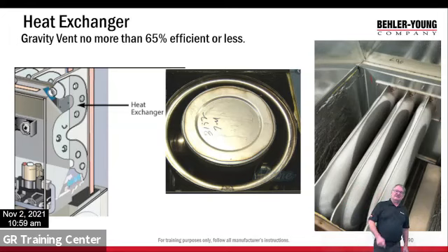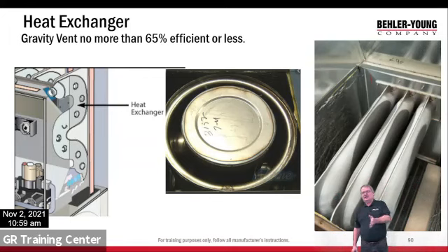All right, the one in the center is a big old tank heat exchanger. This would have been an older style furnace, old lowboys, we used to call them. The one on the left and the one right over my head are modern clamshell heat exchangers, but it's the same concept. If you look over there, you can see the burners in the bottom. The flue gases go up through it, and then they come out the top to the gravity chimney. So the flames are inside that metal heat exchanger, and the air is passing on the outside. We're exchanging the heat from the flue gases to the air. Obviously, if these get a crack in them, we have an issue, because then they can start to leak.